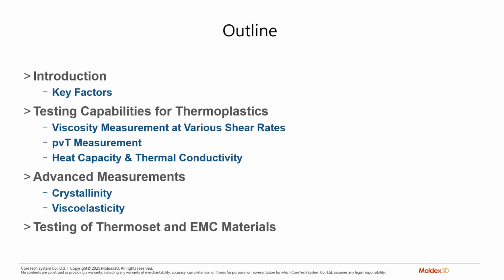So today we're going to be going over some of the key factors of materials in the injection process. We're going to be testing the capabilities of thermoplastics, including viscosity measurement at various shear rates, PVT measurements, some thermal properties like heat capacity and thermal conductivity. We'll also be going into some of the advanced measurements we do, such as crystallinity and viscoelasticity tests, as well as some of the details of testing for thermoset and EMC materials.